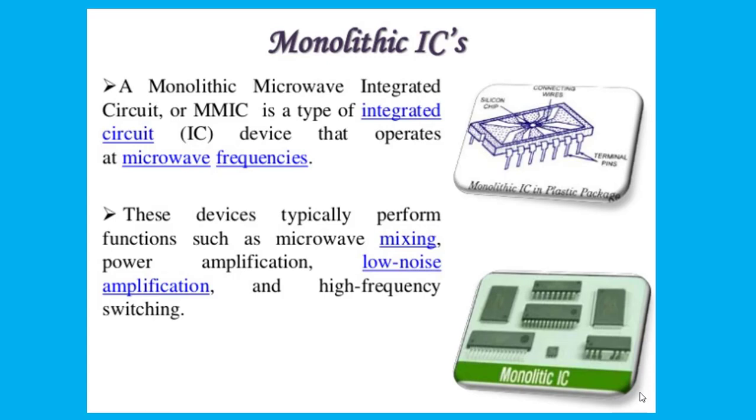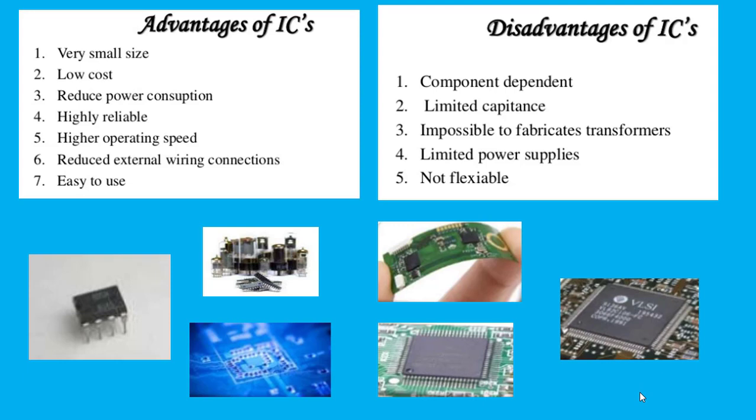ICs have the advantages of low cost, low power, smaller size, and high reliability over discrete circuitry, except in very specialized applications where a circuit must be custom-made to meet unique requirements. ICs are principally used to perform low-power circuit operations such as information processing. ICs cannot handle very large voltages or currents, as the heat generated in such tiny devices would cause the temperature to rise beyond acceptable limits, resulting in burning out of ICs.